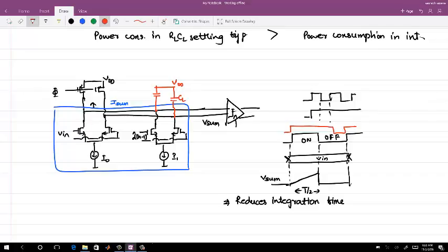So can you realize the difficulty in generating a 10 picosecond narrow pulse? What you are saying is right, and that is actually being done at lower speeds, where you can create a small reset period, which is maybe 10% or 20% of the whole bit period. But at higher speeds, this will not be feasible.